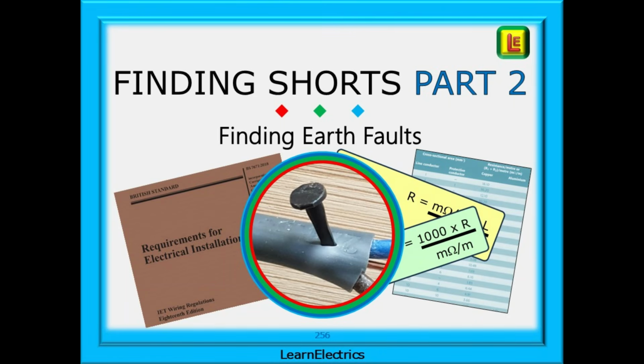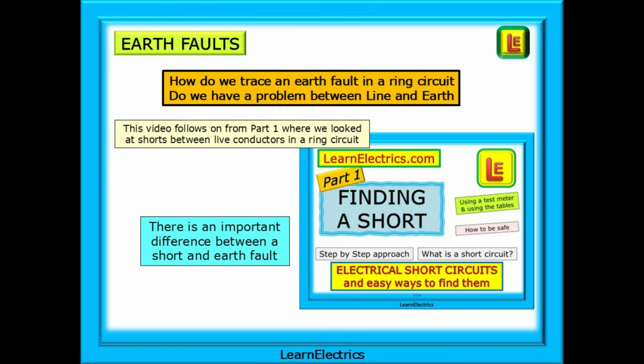This LearnElectrics video looks at finding earth faults in a domestic electrical circuit, although the principles can be applied to many electrical wiring faults. We show you two different methods and also offer other tips. Specifically, we are looking at earth faults in the video, answering questions like how do we trace an earth fault in a ring circuit, or do we have a problem between line and earth.